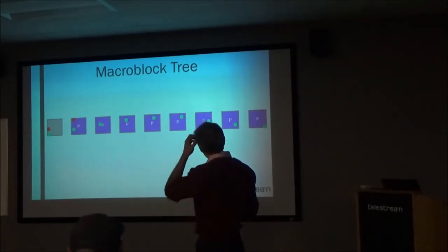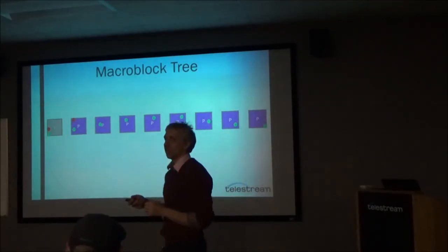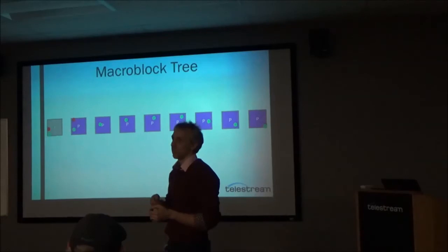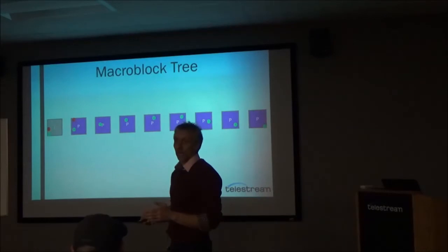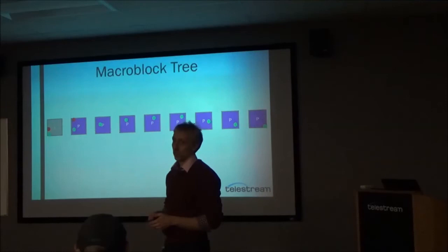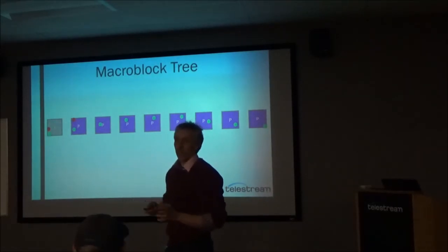One more thing just to say before we move off H.264. The way these specifications are defined is from the point of view of the decoder. So the specification that MPEG or whoever's making these specifications produces tends to say, this is what the bit stream should look like. If you see this, the decoder should do this. It doesn't make a lot of reference to how an encoder should work. And what that does is it leaves the encoder vendors a lot of ability to innovate in the way that they're creating these bit streams.